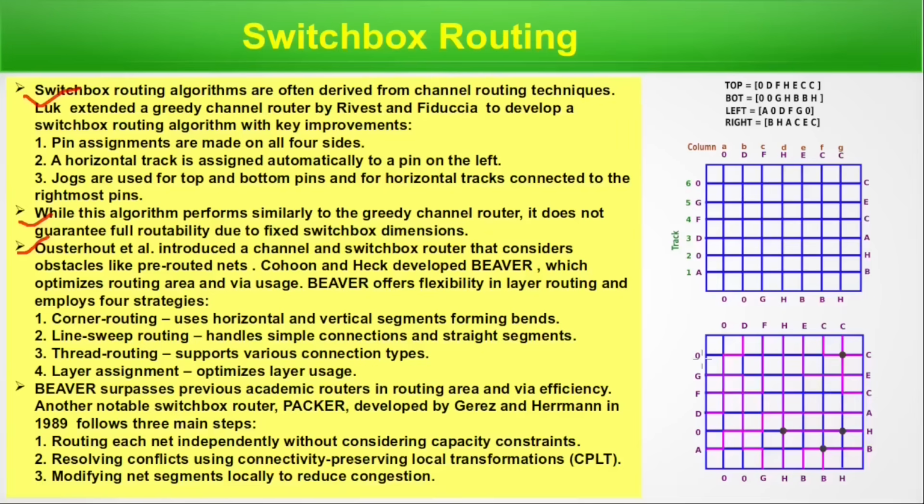This zone where pin connections come from all sides, this complicated portion, is routed by switchbox routing. Look, D is routed like this. G is a little bit complex here, G is like that, F is like that. So top, bottom, left and right pin connections are mentioned. This is the initial and this is the final scenario, how it should connect.